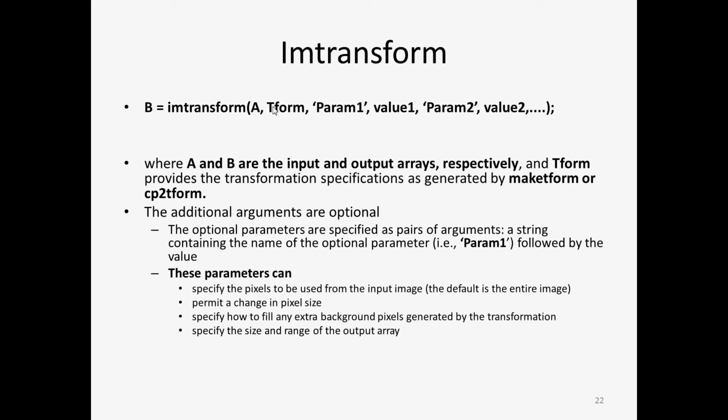Particularly, you can allow or not allow the pixel to change in size, because remember that when you do some operation like rotation or stretching, the image changes size. Do you want to change the size of the pixel according to the transformation, or increase the size of the image, limiting the size of the pixel? All these things are supported by imtransform.